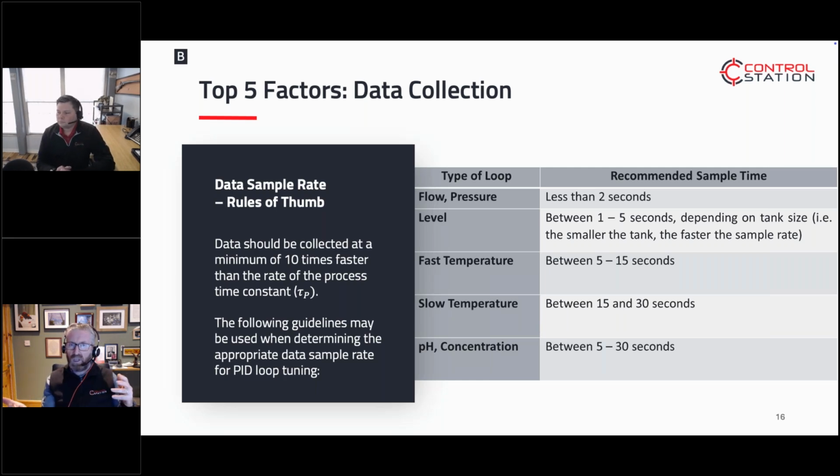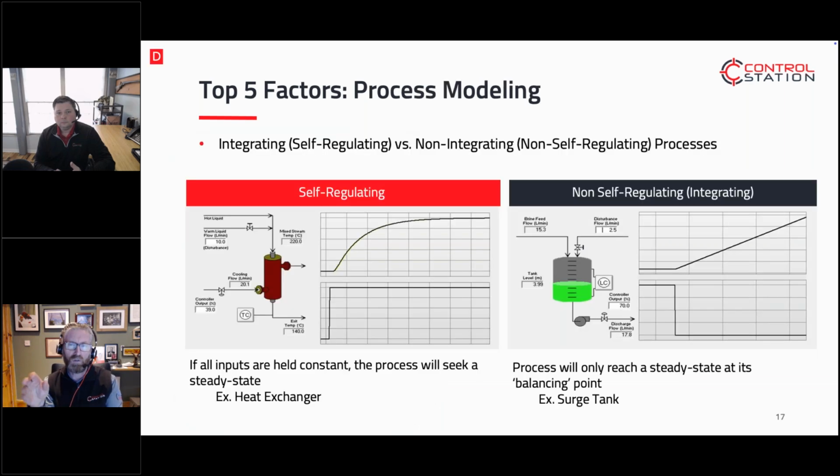Actually, I find the biggest difference is between greenfield and brownfield sites. Modern systems that have had an upgrade are now all on 1 second data. That's our standard now, which has been really good for us and for tuning, because it means consistency. Sometimes you have to negotiate and look for a slow rate and a fast rate, but from that information we can go and generate this model.